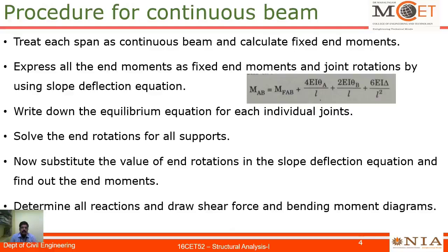So next one is the procedure to solve the continuous beam. We need to treat each span as a fixed beam and calculate the fixed end moments. Next we need to express all the end moments as fixed end moments and joint rotations by using the slope deflection equation.